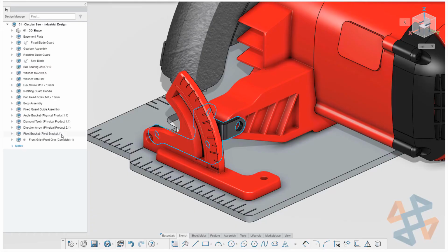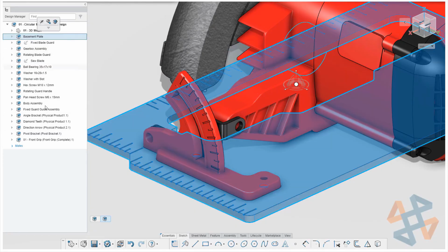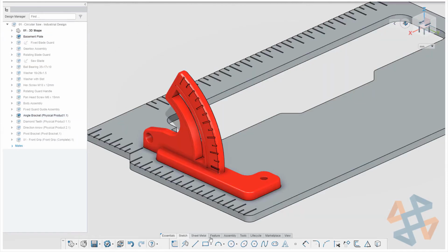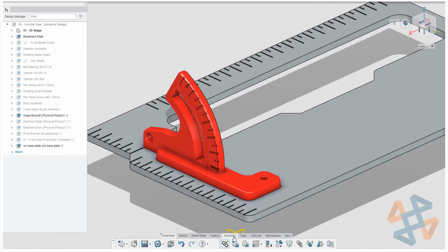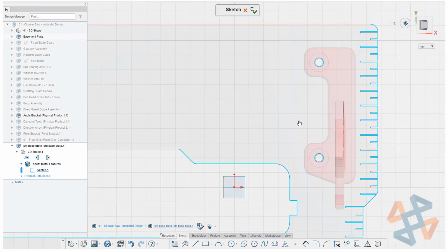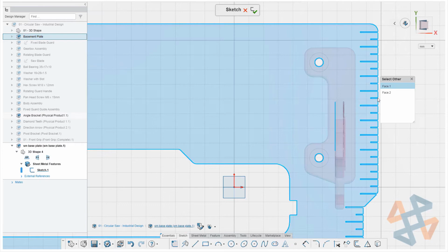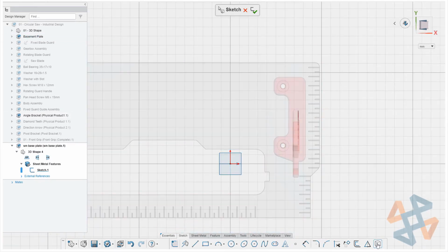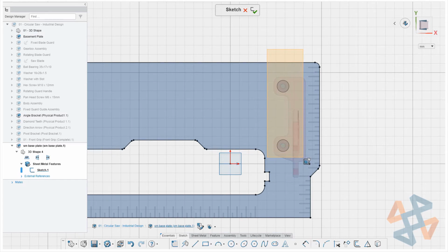Let's look at the new Xshape app for the 3DEXPERIENCE platform. This angle bracket and base plate are going to be pretty expensive to manufacture. So we're going to go ahead and try to make this into a sheet metal component instead. Grabbing the bottom face of this base plate will give us a sketch needed to begin our sheet metal part. We don't need those holes because that bracket's going to become part of the sheet metal component.